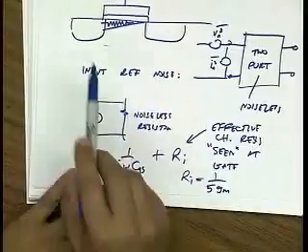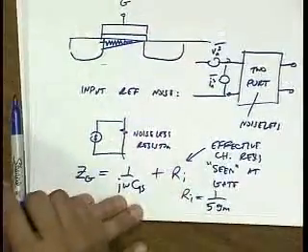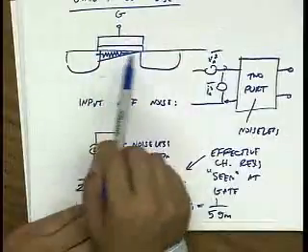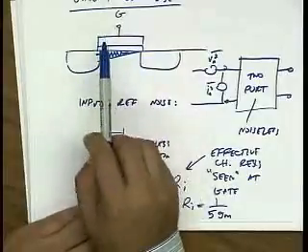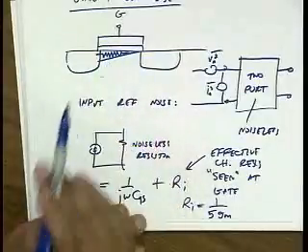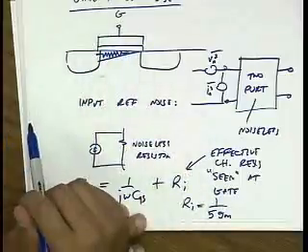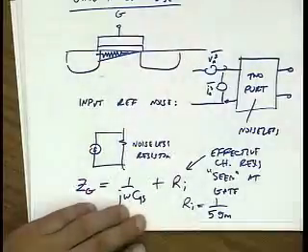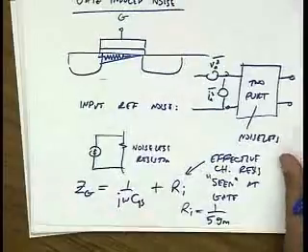And since you see part of that channel on the gate, there's going to be thermal noise at the gate. Of course, this noise is correlated to the noise in the channel because it's the same noise source. It's not a new noise source. It's the channel noise appearing at the gate. So keep in mind that when you look at the gate of a FET and you talk about the noise seen at that port, it is going to contain some of the drain current, and it's going to be correlated to the drain current. Because it's correlated, it makes things a little bit more difficult to handle. But we can handle it. We'll see that next lecture.